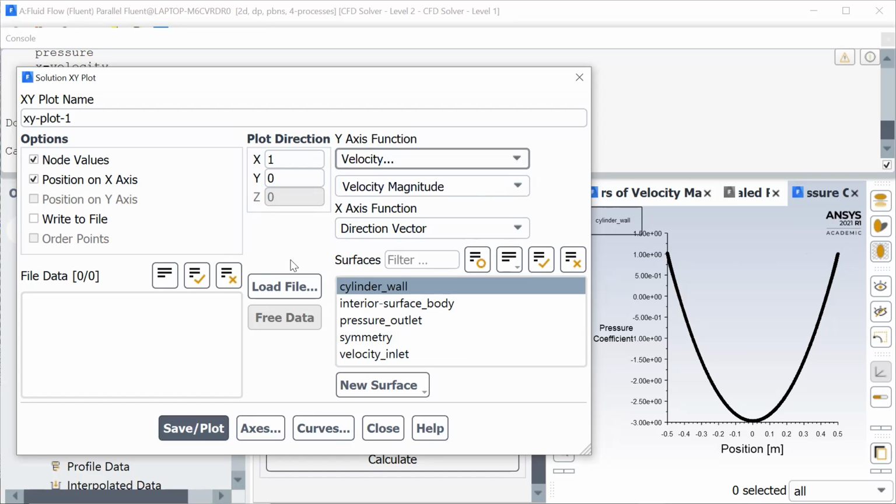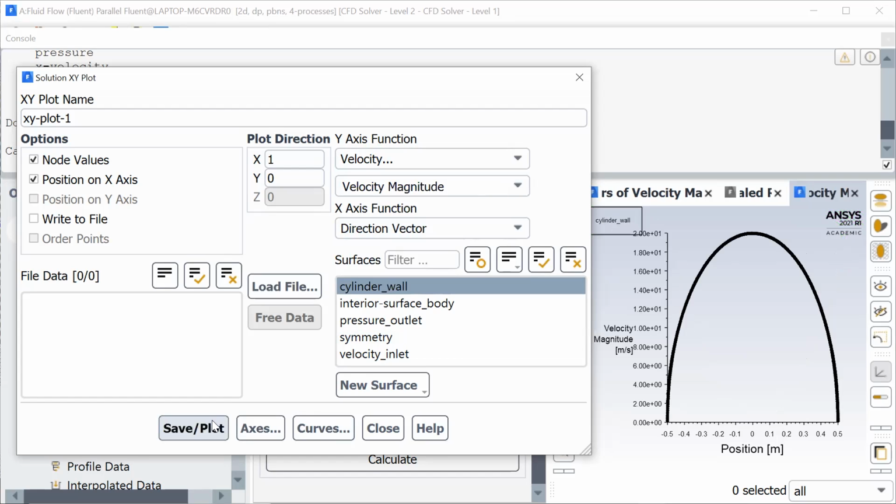And then velocity, I think I explained this earlier. Hopefully you know what you should be getting. Okay, no, I didn't, because I was talking about the turbulent case. So in the turbulent case and laminar case, we have a no slip condition. So on the surface, we're going to have 0 velocity unless we have our rotation. I would like to have explained that, but unfortunately, I don't have those results. Then you can see basically just our general shape, where the velocity is maximum at the top and bottom, and then you have your stagnation points at the front and back. So that's good.